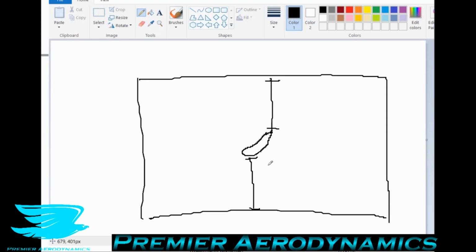It doesn't matter. If the box is a little bit smaller, which you may do to reduce the number of cells you need, then that may not be such a good idea, because what happens is the flow comes over the wing and then it gets redirected up because this is producing downforce. If this wing was producing lift, then you have the opposite thing occurring where the flow will be going down after the trailing edge. But in this particular case, it's going up.